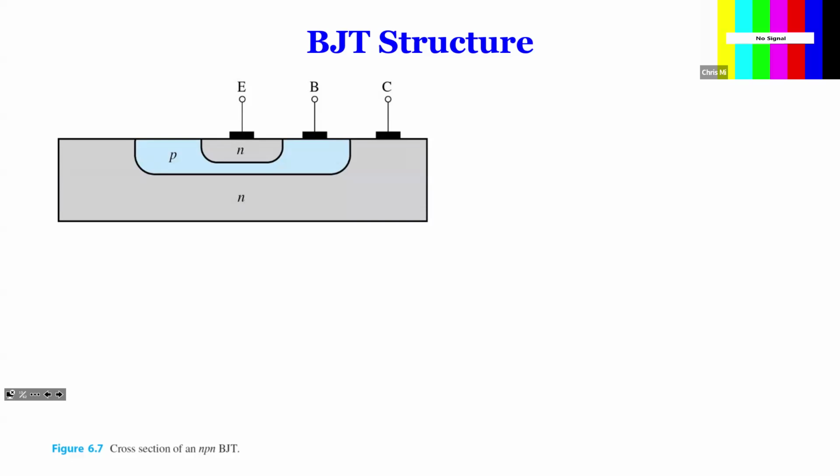They dope the material with impurity. And then on that silicon, they dig a well, and in that well, they dope a different material to form P-type material. And then on that P-type material, they dig another well, and then they put N material. So now you have NPN formed like this, right? And then base in the middle, and E is on top and a collector on this side.